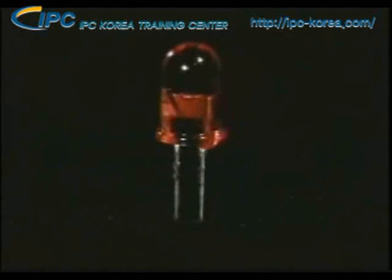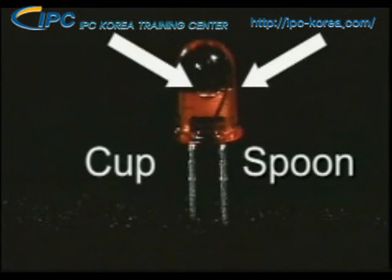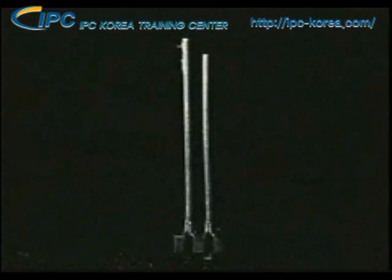Polarity is typically indicated by the location of the cup and spoon inside the lens. The cup is associated with the cathode or negative lead. In some LEDs, the negative lead will be shorter, or there may be a plus symbol on the positive side.